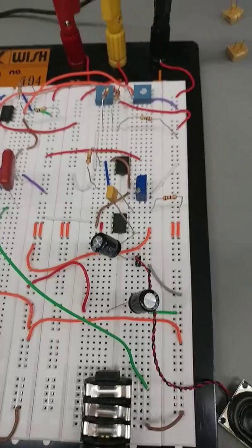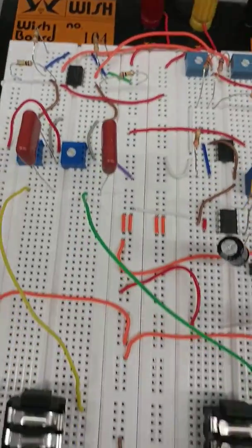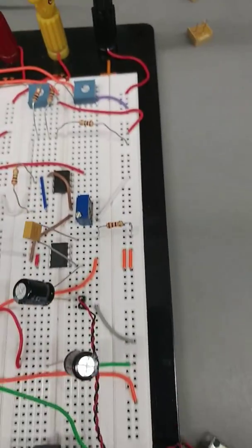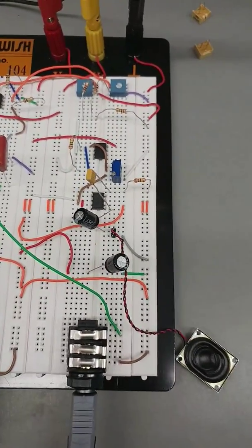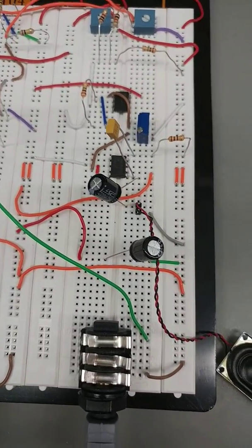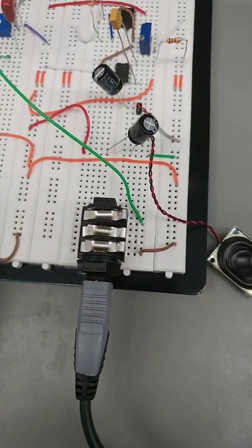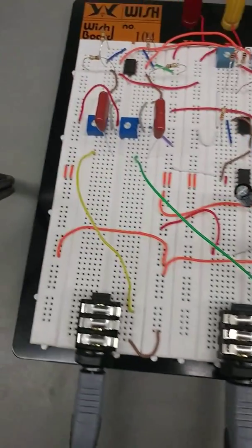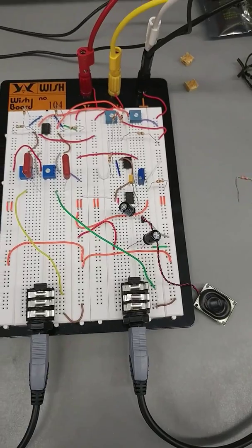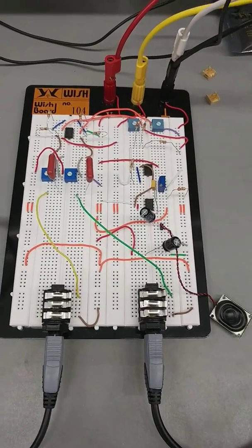Now we also had to use this 220 microfarad cap right here between the positive red terminal all the way down, which is that red jumper, and that green jumper to ground, which is shunting our power supply because of our peak currents through all the op amps and systems. Then we have obviously our input to the entire system. So now I'm going to try to demonstrate to the best of my ability what is actually happening with the system.